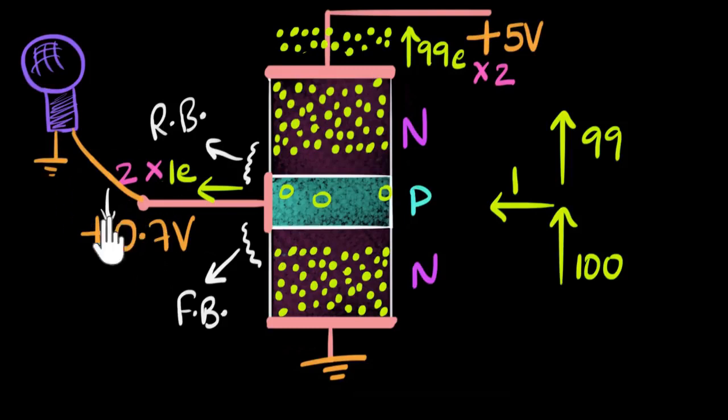Of course, the engineers will make sure that the voltage over here will never go below 0.7 volt and all of that stuff. But don't worry, this voltage will fluctuate pretty much depending upon your sound. And as a result, the current in this wire will also fluctuate depending on your sound. Now guess what? The current in this wire will fluctuate in exactly the same manner as the current fluctuates over here. That's what we saw. But it is 99 times more, so it's amplified.